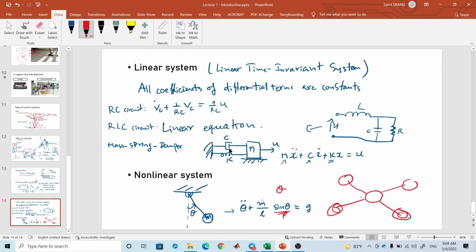And you see the mass spring damper also. The damper we can make in a certain way, using fluid inside a cylinder with a small pipe that allows the fluid to move, and also the spring, you make a nice shape of the spring with a constant profile. Let's say you have an extension spring, then you can have a linear system.